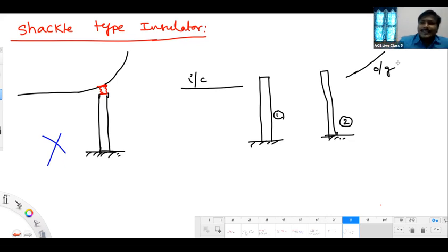See, in order to increase the mechanical stability of the conductors on the poles, what we are saying is that the incoming conductor will connect to pole 1, and the outgoing conductor will connect to pole 1, so that incoming and outgoing conductors are perfectly mechanically stable. You can't connect this conductor directly to the pole.